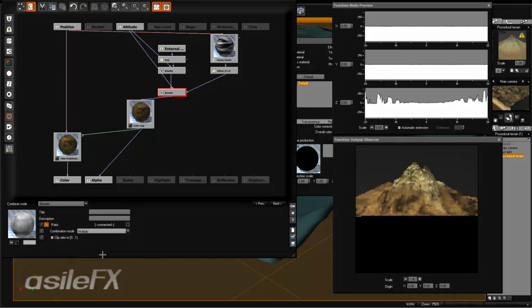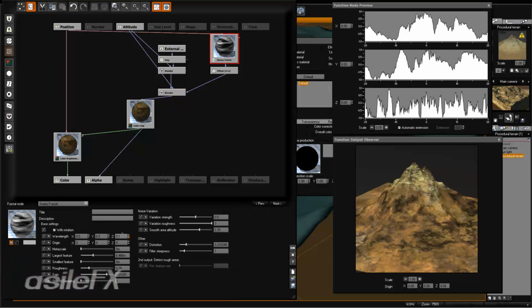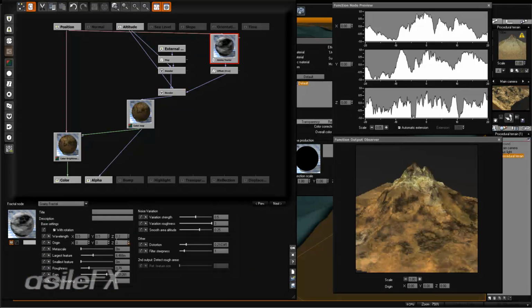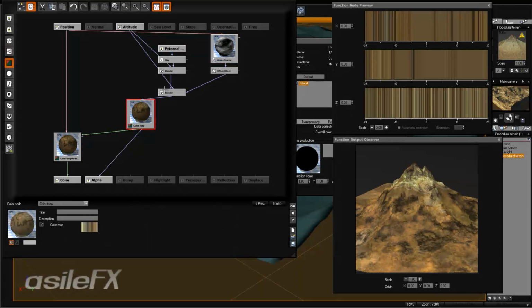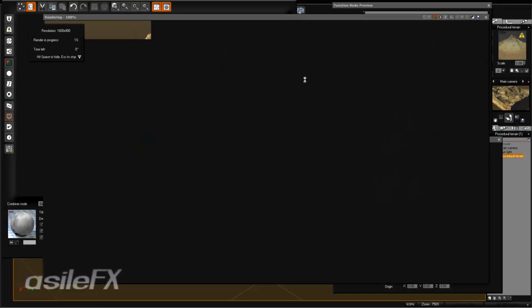We could also have an additional subtraction. We could set it to a multiply. You really just want to play around with it and see which way is going to give you the best looking terrain, or whatever it is you're going for. I'm going to change this wavelength to 0.2 on the Z for that Grainy Fractal. So now I have this set to multiply.